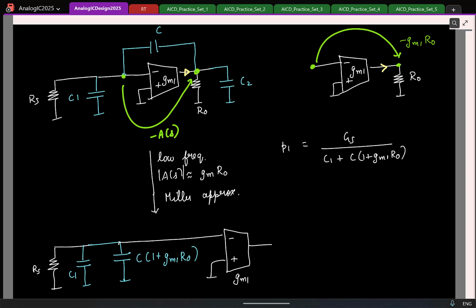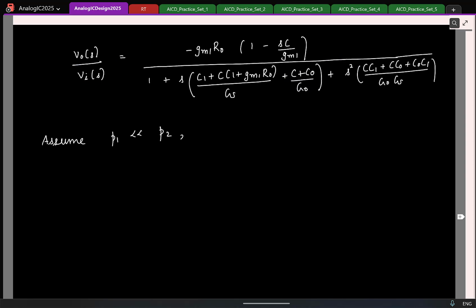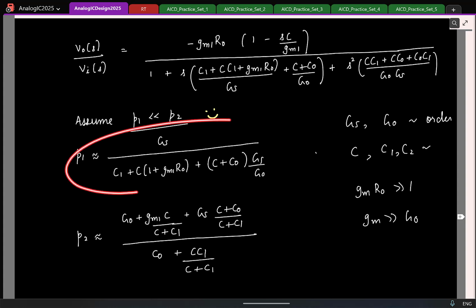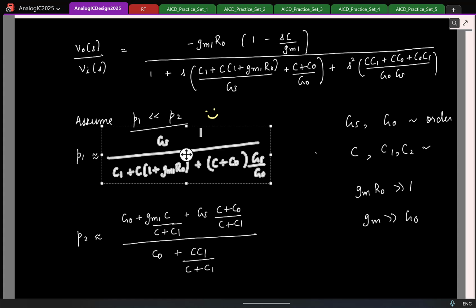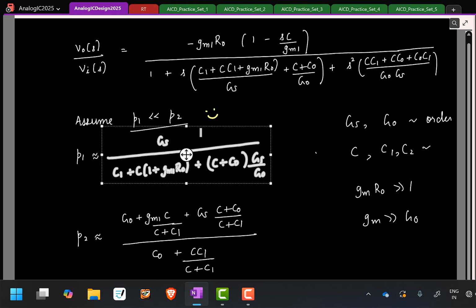Again, remember we are making an assumption that we are dealing with low frequencies, which means the pole we compute is a low frequency pole or high frequency pole. If this pole is indeed a low frequency pole, our assumption is fine. But that is something we already kind of verified when we solved the quadratic equation. So when we solved and got the expression for this pole, we already convinced ourselves that this is a smaller frequency pole. So it is okay. And if I compare the result I got by solving the quadratic equation approximately and what we got from our intuition, oops, okay.